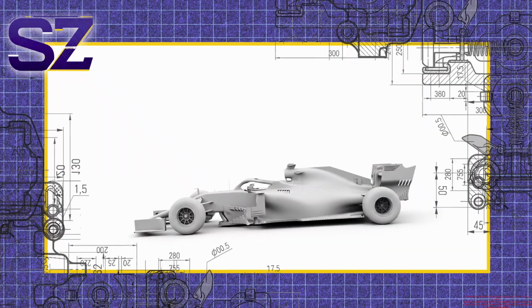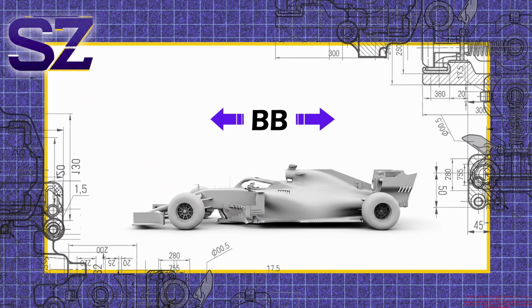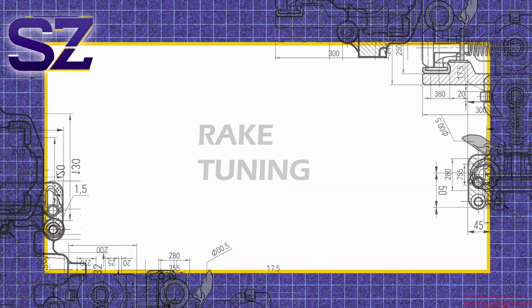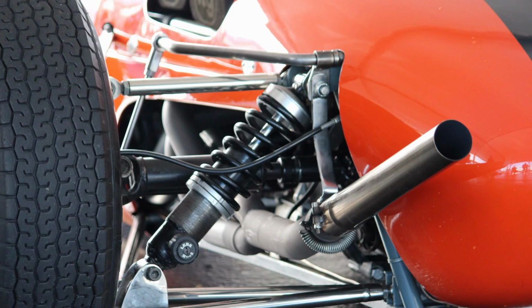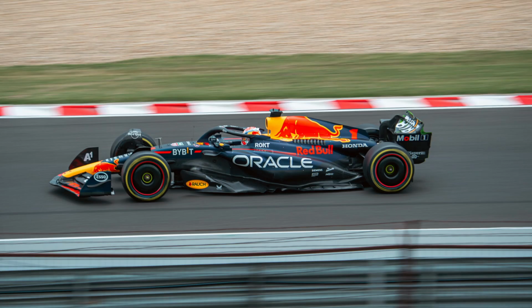First is brake migration, dynamically shifting brake bias rearward during braking to reduce front locking, which can be done by the driver themselves. Next is rake tuning, where you adjust the front to rear ride height to position the center of pressure more carefully. You can also adjust the suspension stiffness, softening or stiffening springs to manage how quickly the load transfers and where it settles. And finally, you can also look at the weight distribution, which is the fixed placement of heavy components such as the engine, fuel tank and driver, which define the base center of gravity.